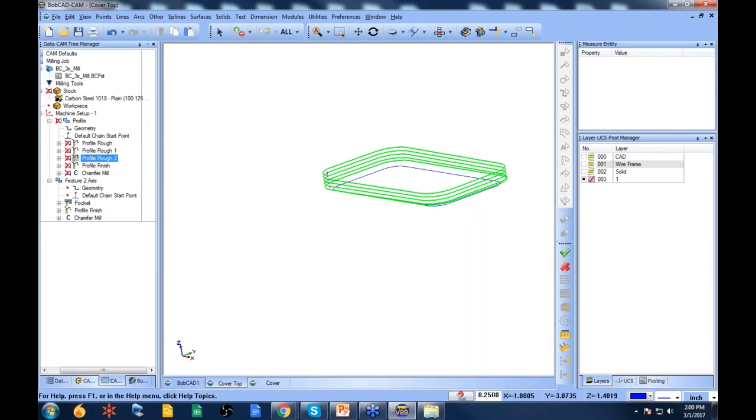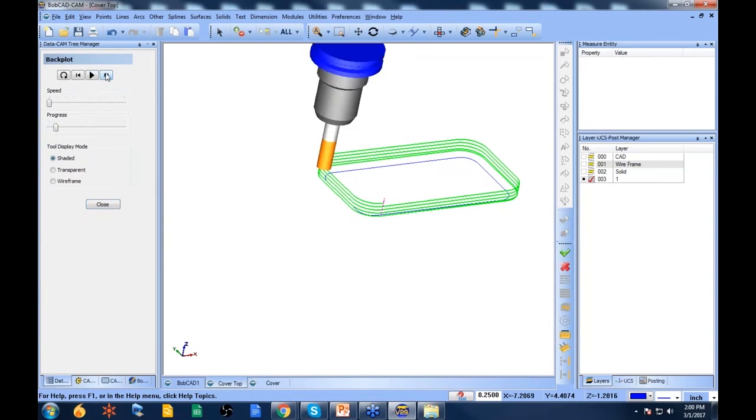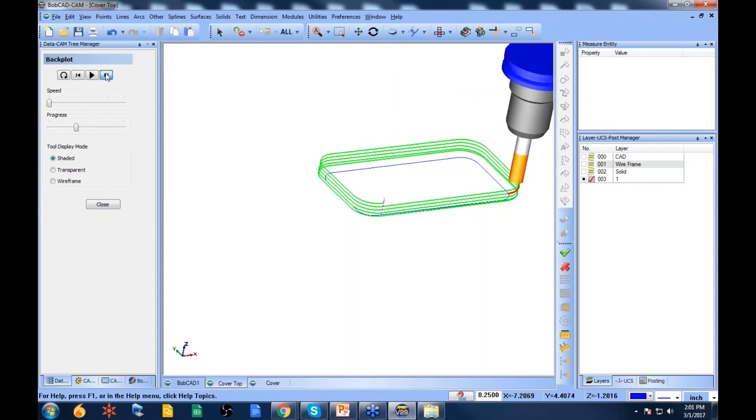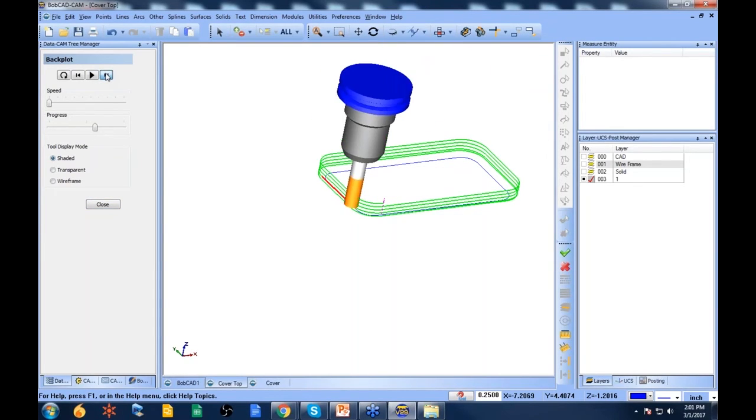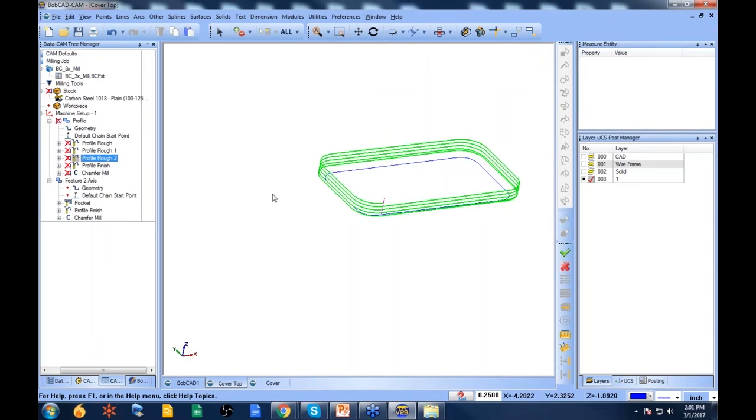So the question is, can I helical mill shapes other than circles? Yes, you can helical mill or ramp profile irregular shapes. You can do it for slots. You can do it for circles. Or in this case, we're ramping around a rectangle shape. You can use this with larger tools. A lot of times this is a quick way to hog out a bunch of material. Just follow the profile and ramp your way down, okay? So yes, you can helical mill other shapes than circles, and you do it by the profile pattern contour ramping.